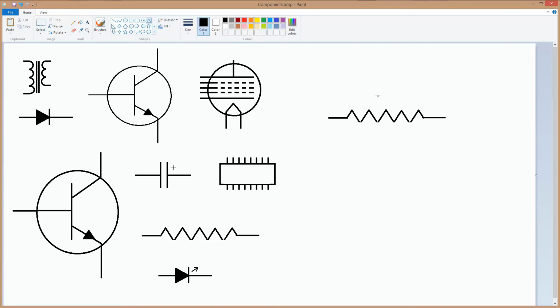Of course, this triangle is going the wrong direction and the line size is wrong, so I need to go up here and change my line size back to the correct size, and then I need to flip this vertically. So we'll go to rotate and then rotate vertical, and so there it is. And so now I'll just take that tip of that triangle and connect it to the center of the resistor, and then use my select tool to cut away most of it. And now we have the contactor that's going to our resistor, and we're going to draw a line straight up, and so there's our center tap on our potentiometer schematic image. So that's really cool, and it didn't take long to make that.